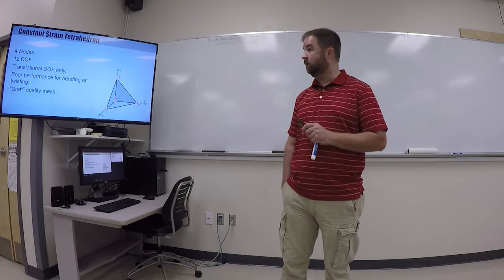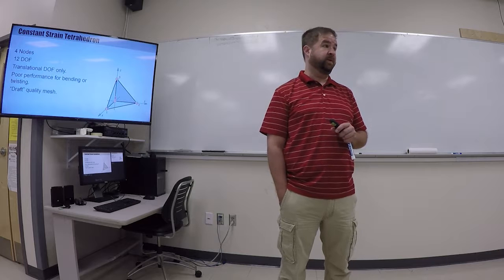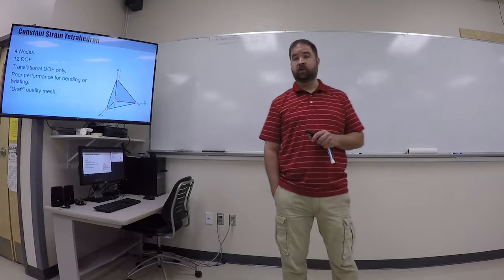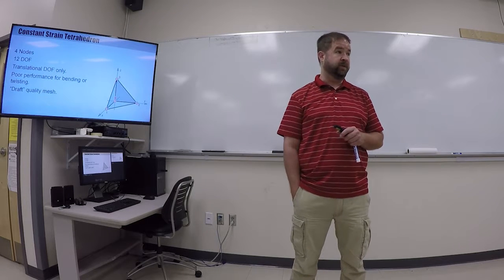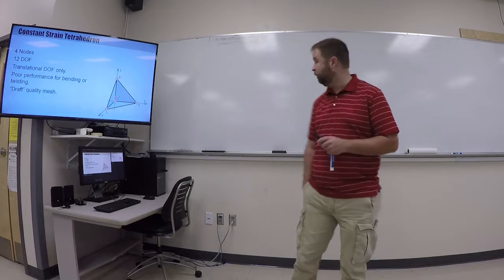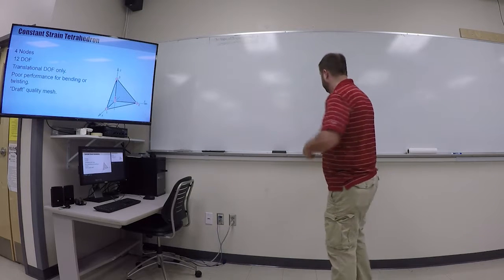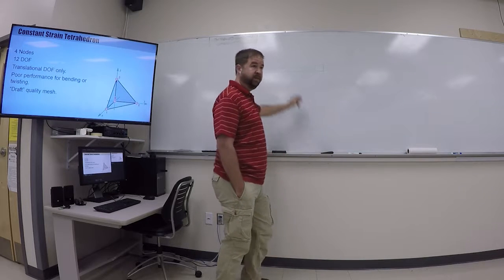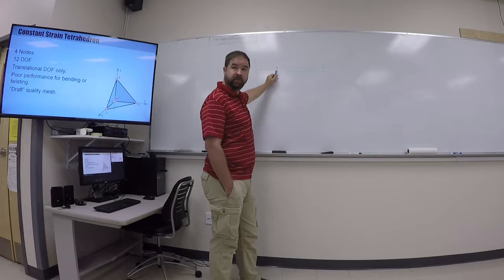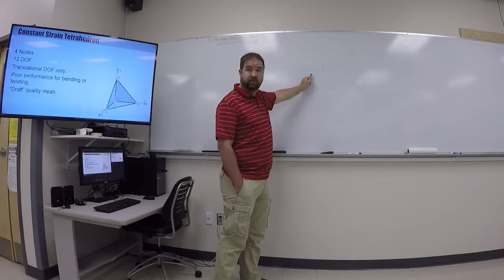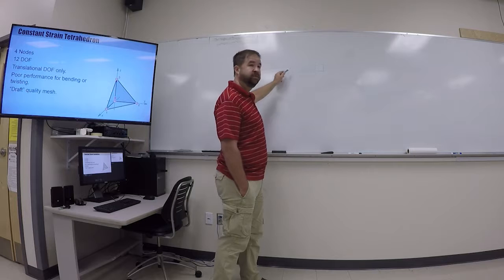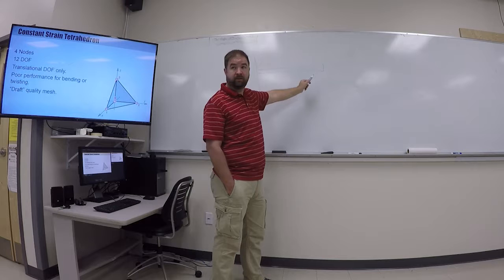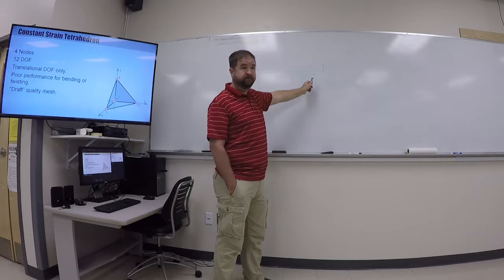Okay? These are now fully three-dimensional elements that can be modeling things that don't have any symmetry, that have irregular shapes that we can't simplify down into something simpler. Okay, so my point early on was if I have a cantilever beam, I should probably use a beam element to represent that. A one-dimensional element that only has length. It's not worth spending the time to define all the geometry when the cross-section is constant down its length.